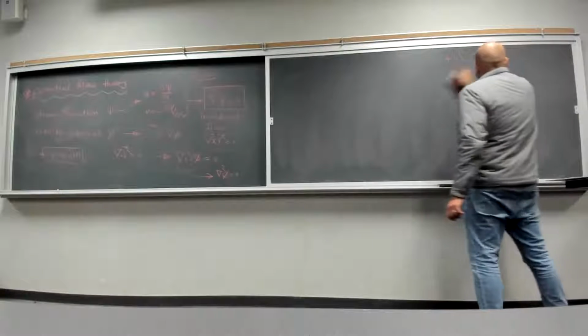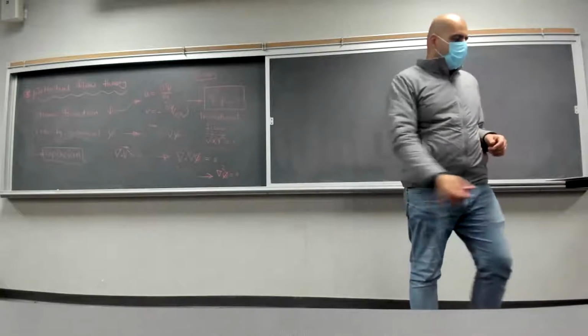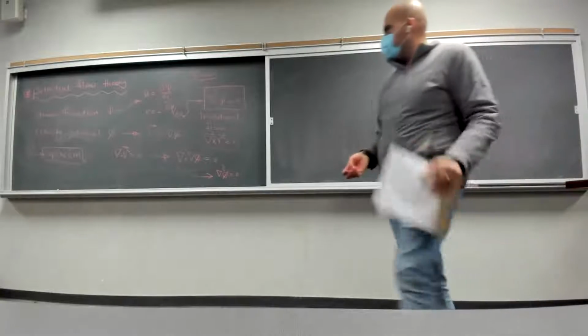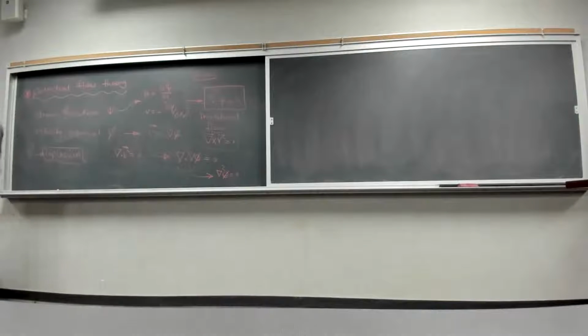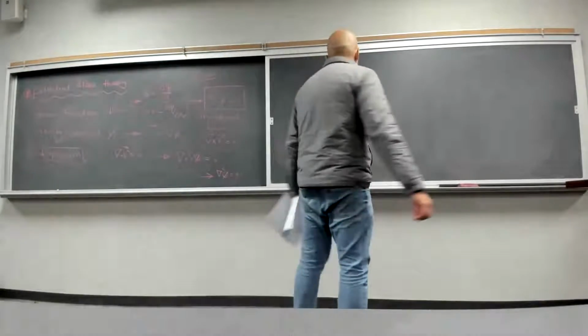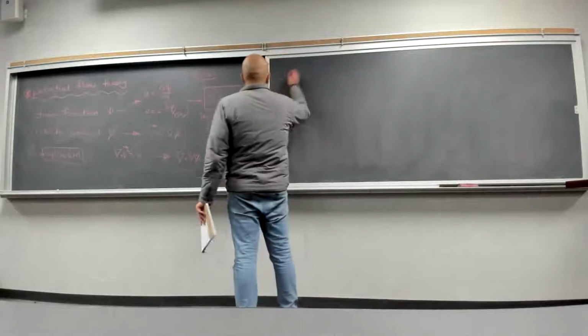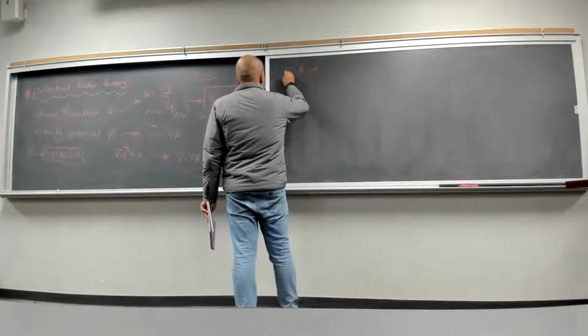Okay, so for an irrotational incompressible flow, we understand that the Laplacian of the stream function and the Laplacian of the velocity potential are both 0. But why is this important? Why do we need it? Where are we going to use this? It goes back to the definition of this type of function. The Laplacian of any function is 0.